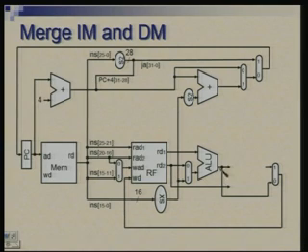So, that means the ALU which was supplying the address, this will go back and supply an alternative address. This was the data input, this will go back to this point, and the data which is being read will actually now come out here. So, these inputs and outputs which were connected to these will now be rerouted and brought back to this particular block.